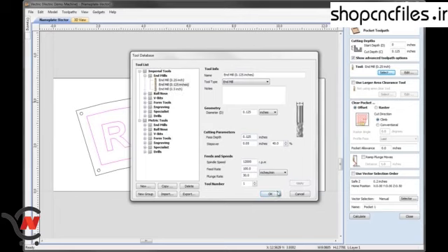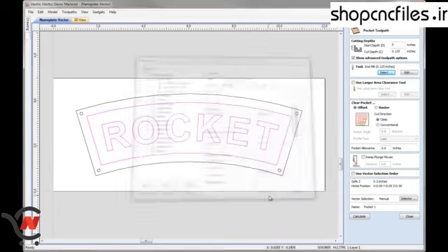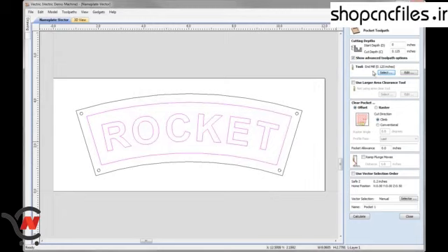I'm going to hit apply, and you can see where that's added that in the list. And what I may want to do is just adjust its position in the list by dragging that up and letting go of it here. So now I've got the 1/8, the 1/4 and the 1/2 inch tool. In this case there's my 1/8 inch tool. I'm going to hit apply and OK. So there I've got a 1/8 inch end mill selected.